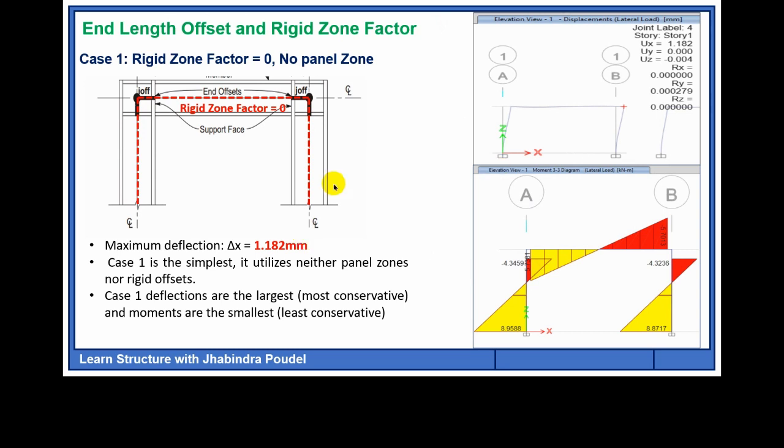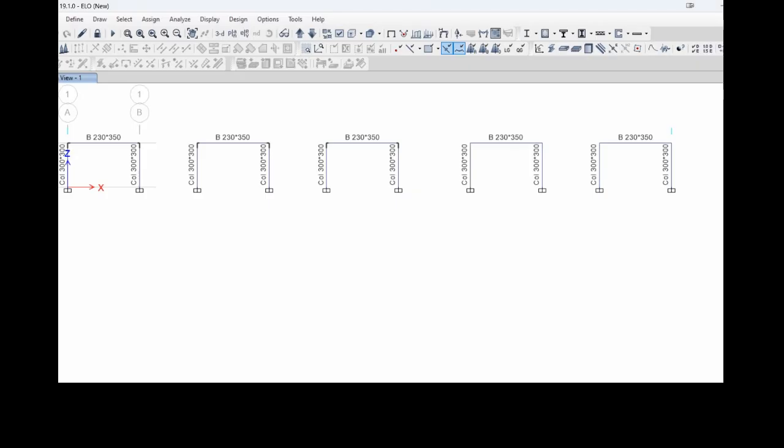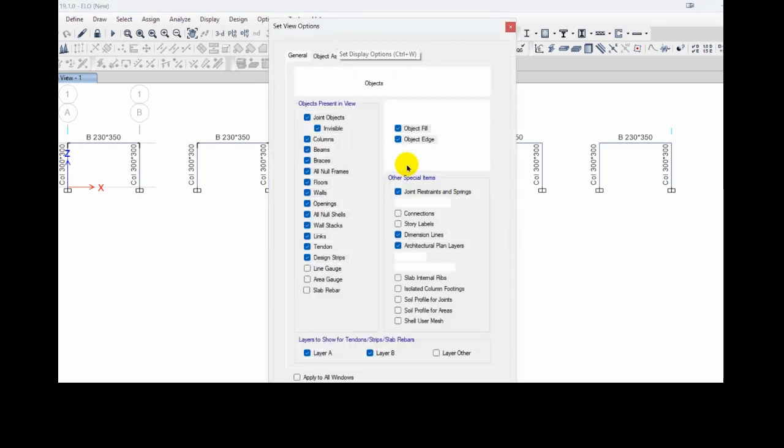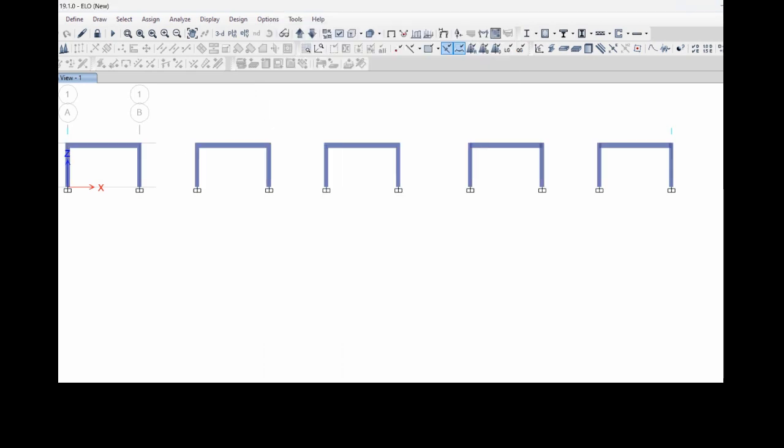The analysis is based on the center-to-center line or joint-to-joint geometry of the structure in ETABS. If we look into ETABS, the modeling can be done with line elements for structural elements such as beams, columns, etc. While doing this modeling, the structure has a definite cross section, although here represented as a line element. If we extrude this view, the actual dimension of the structure can be seen.